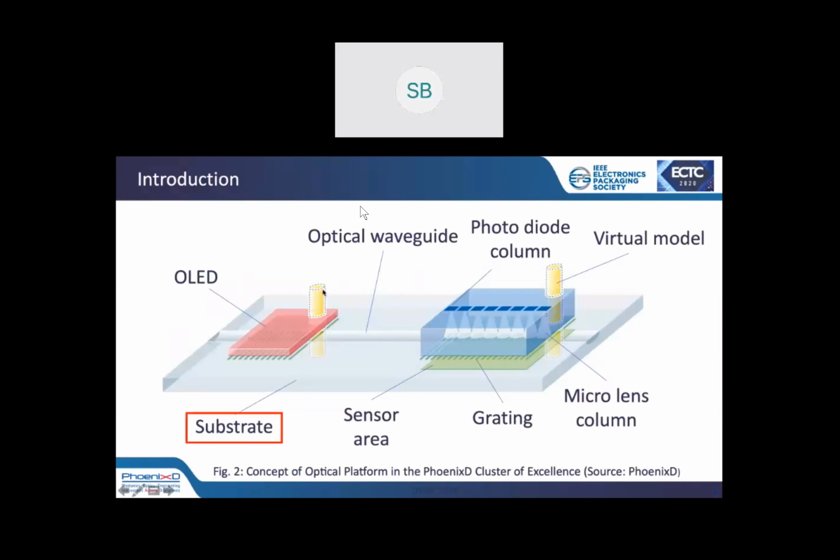All right, let's come to the concept of the pocket and the laser diode. If we look at our substrate in this picture, we can see a pocket. The pocket is for adjusting the laser diode towards the waveguide, which is inserted into the channel. The laser diode is contacted by laser direct structuring on top and on the bottom. The bottom connection is done with a via connection, a vertical interconnect, which is also performed by laser direct structuring.